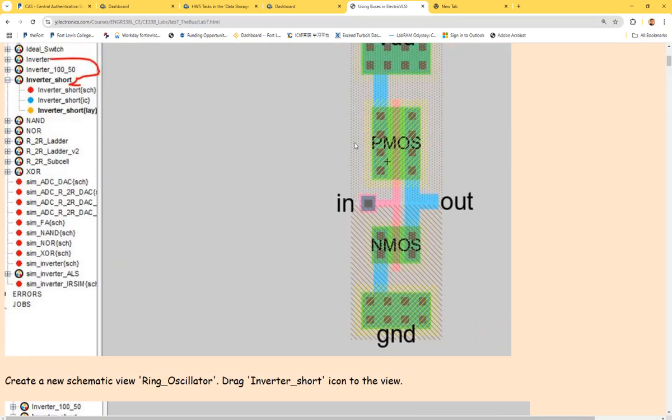One quick question: can you drill a metal 1 on the top of this guy? Why or why not? Can you let the metal 1 trace run across the transistors? So what I meant was, if I lay out like this, right?